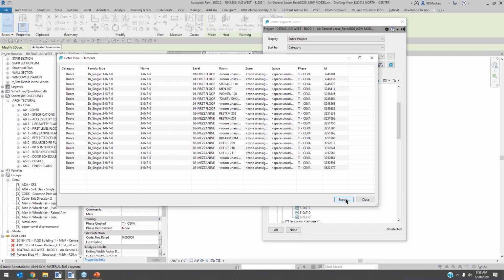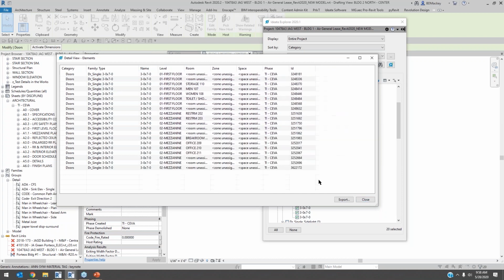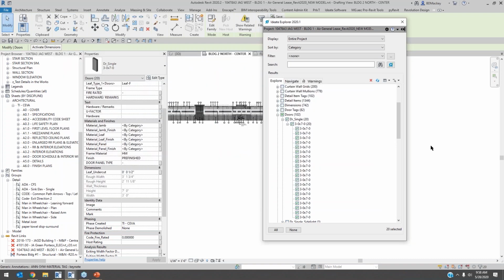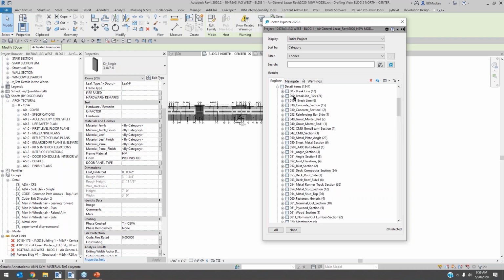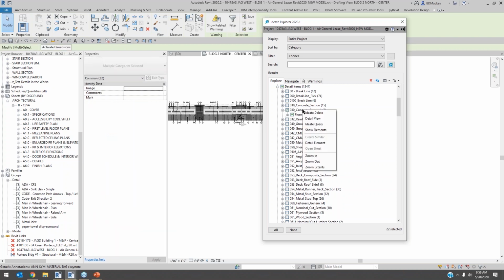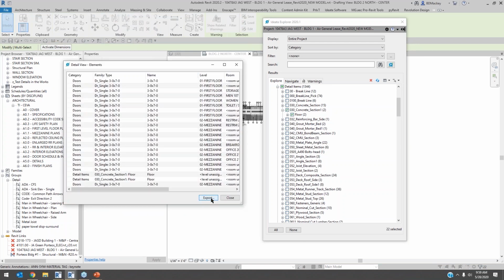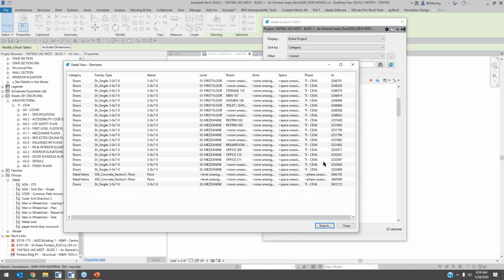And then if you were having issues with this, you can simply export it. One of the things on here, if you are in a work shared environment, is that it does tell you what workset those elements are on. I had a client with two different architects working the view, and somebody put in a non-standard family, and they said, no, we didn't do that. We want to know what views those are in because we're pretty sure you did it. There was this finger pointing going on. So literally it was me. I found that detail item family, selected it, right-clicked on it, and said give me a detail view. It told me what the workset was. I exported that and gave it to them. It took me 10 seconds to find every single view that one detail component was in.